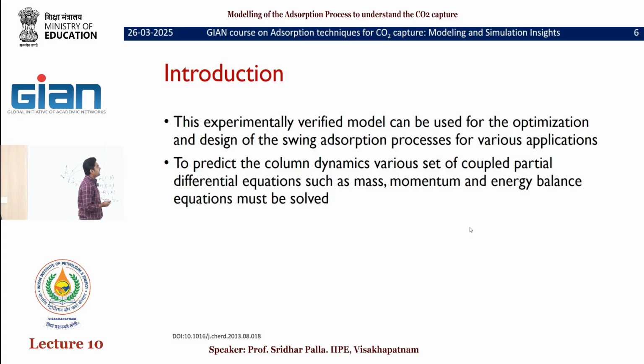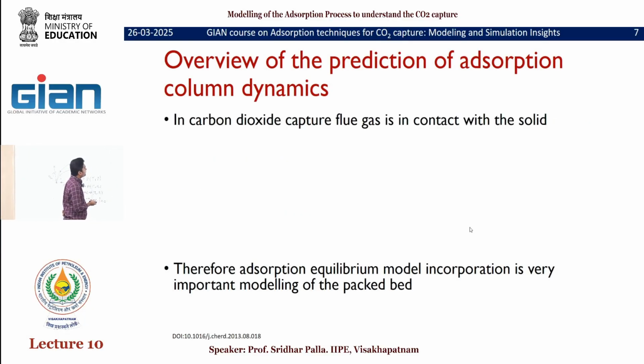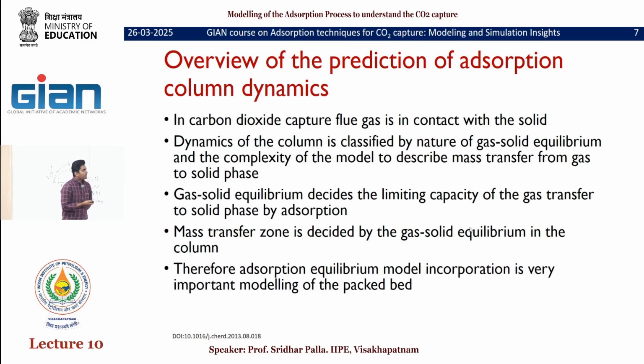So, to predict the column dynamics, we need a various set of coupled partial differential equations. We will see all those equations, various PDEs with mass, momentum and energy balance equations, which must be solved. So, I will go through the overview. In this particular study, when we have a source that is a flue gas in contact with the packed bed, we have a gas solid phase. We have two phases where CO2 will come in contact with the solid adsorbent.